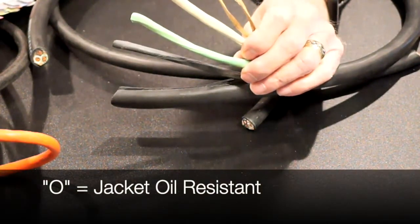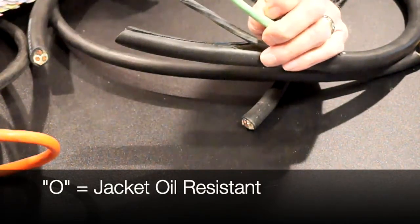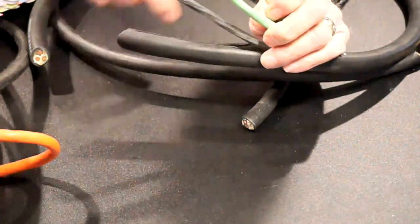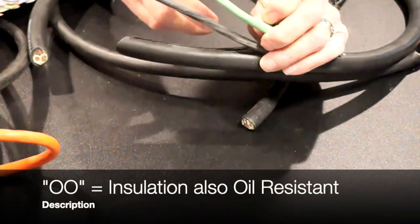The first O tells me that the outer jacket is oil resistant. In fact, the table tells me it's an oil resistant thermoset. The second O tells me that the insulation itself is an oil resistant thermoset.